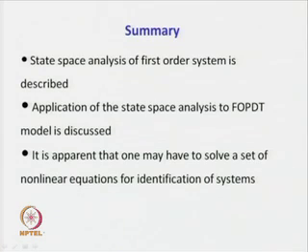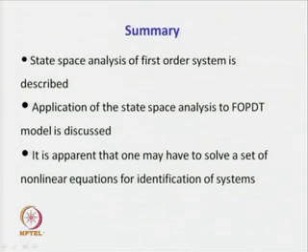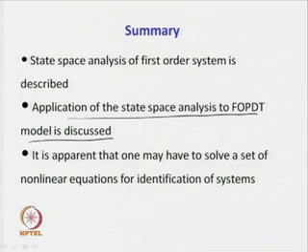What we have learned from this lecture? That state space analysis of first order system is described, where we have been able to derive simple expressions that can be solved simultaneously to estimate unknown parameters of a first order plus dead time model. Also, we have seen that application of the state space analysis can be extended to identify simplified models. How that can be done, that we shall discuss in the subsequent lecture.